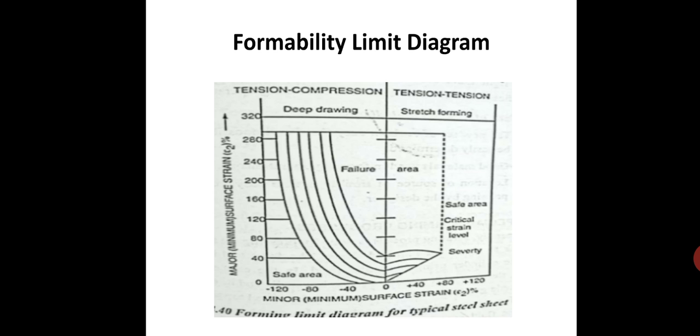During the pressing of the sheet metal, the concentric circles are stretched into an elliptical shape. Here the major and the minor axes of the ellipse give the directions of the principal strains.